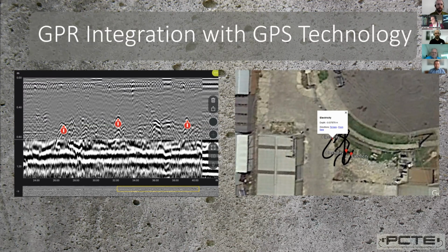So here's another one that was done recently in Melbourne. We're just looking for a power conduit that was running from a parking lot to commercial buildings that were being put in. I've just marked it several times in red. You can see in this scan that with the GS8000 at the top, you can see each individual bar quite clearly. It's a stepped frequency GPR, so we get very good clarity of our top layer of reinforcement, and we can also see deeper targets.